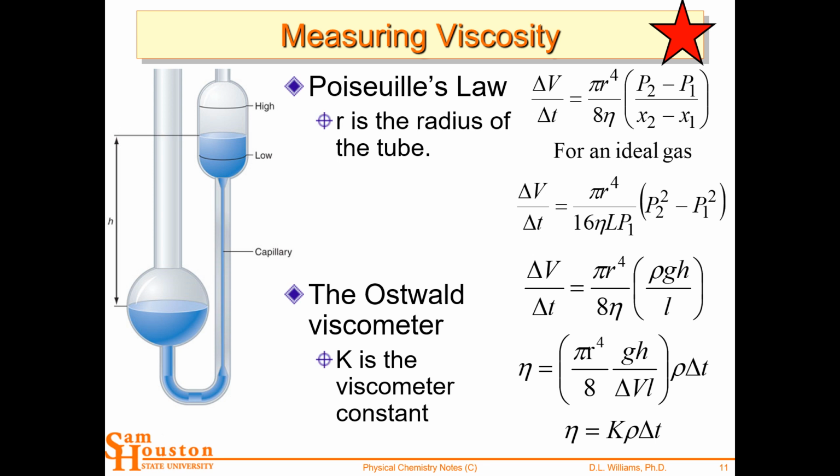Yes. In the equation, the radius, is that the radius of the capillary? Not the solvent? Yeah, in the asphalt viscometer, yes. And then the L would be the length of that choke point. Okay. So this is also a good point that you bring up, and that is it's going to be restricted by the thinnest pipe that you have. So you might have a 1-inch pipe coming in, then a half-inch section, and then another 1-inch section. That half-inch section is going to govern the flow. That's going to be a limiting factor. That's what you base your calculations on.